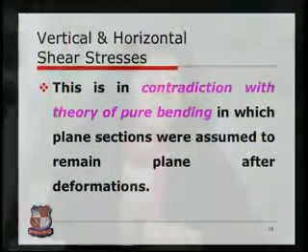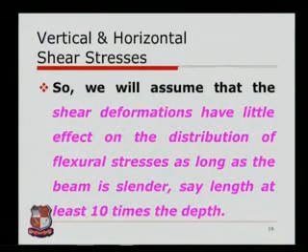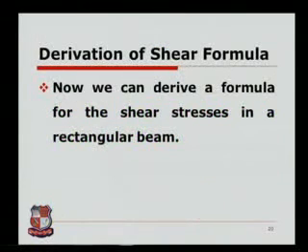So in this particular case it is not the same. In this particular case we are assuming the sections will deform after the loading. So that is a contradiction. So we will assume that the shear deformations have little effect on the distribution of the flexural stresses as long as the beam is slender, so the length is at least 10 times the depth.